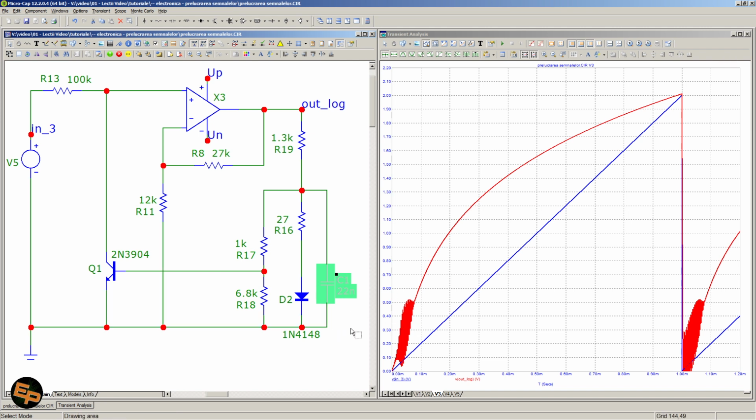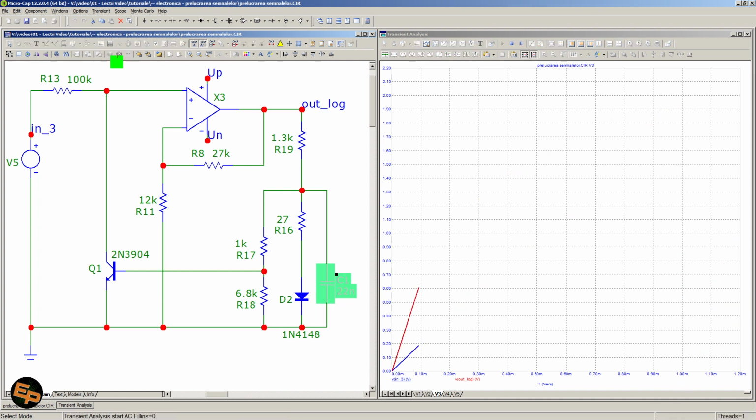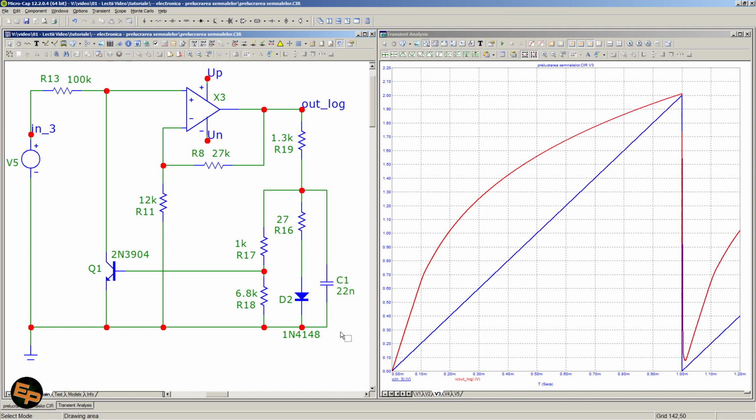Okay, for example, if I disable this capacitor, we see that it tends to have some oscillations. The whole circuit tends to have some oscillations at smaller values. So I needed to place it in order for this circuit to work properly. In practice, you need to see for yourself if in your case it needs to be smaller or bigger, or it can be completely removed.